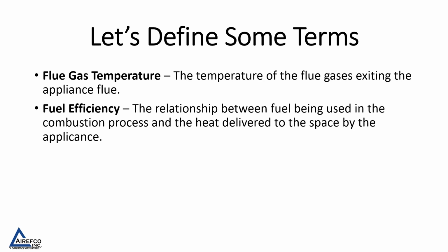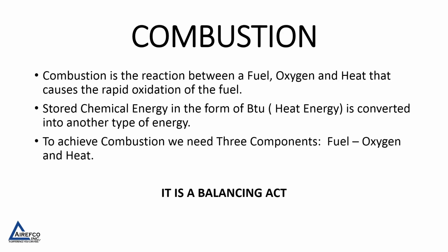Flue gas temperature is the temperature of the flue gases exiting the appliance flue. And fuel efficiency is the relationship between the fuel being used in the combustion process and the heat delivered to the space by the appliance. Combustion is the reaction between a fuel, oxygen, and heat that causes the rapid oxidation of the fuel. Stored chemical energy in the form of BTUs, or heat energy, is converted into another type of energy. To achieve combustion, we need three components: fuel, oxygen, and heat. It's a balancing act.